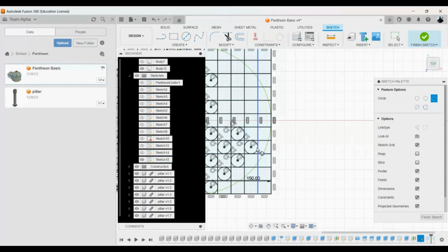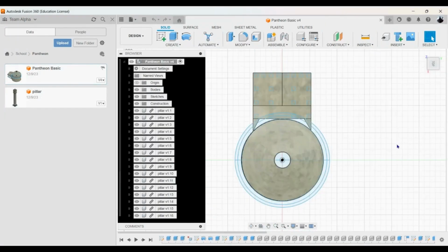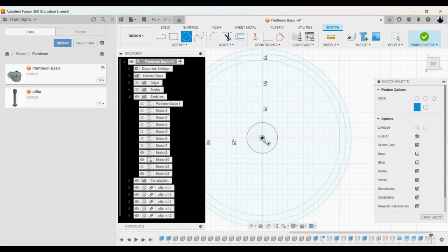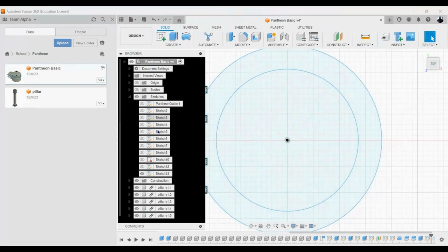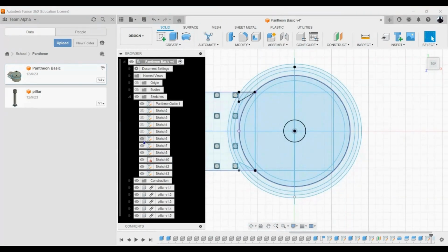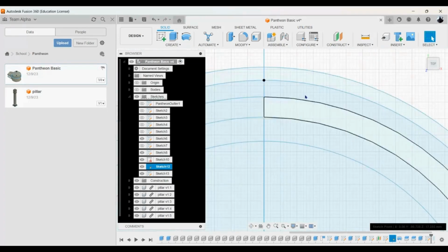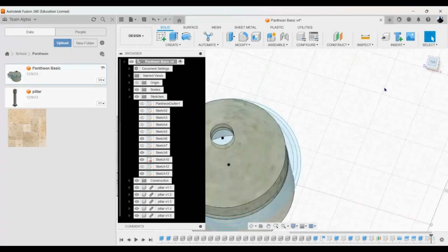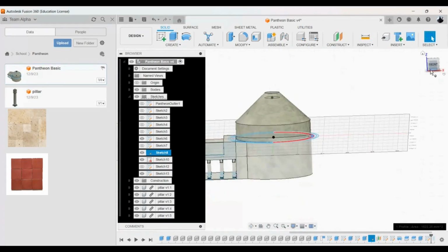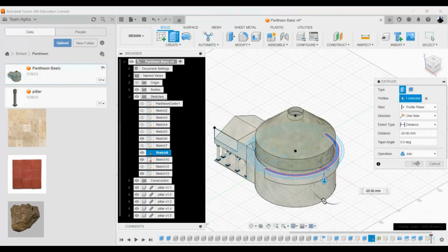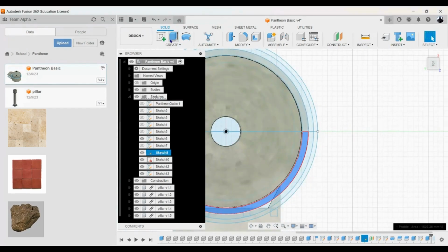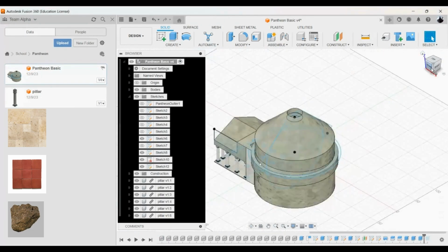The Pantheon's dome exhibits varying thickness, ranging from 6.4 meters at the base to 1.2 meters around the oculus. The construction materials diversify at different levels, starting with travertine at its thickest point, followed by terracotta tiles and culminating with tufa and pumice at the pinnacle. The oculus strategically lightens the load at the dome's vulnerable apex.